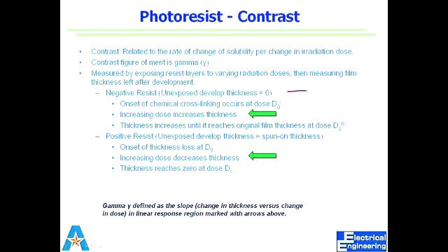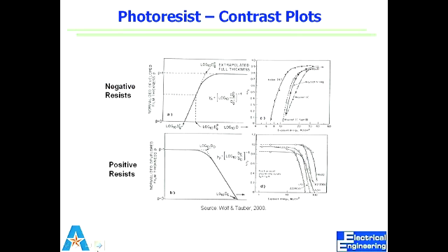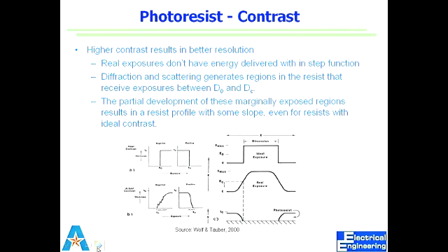That you start with unexposed thickness, which is 0. In this case, you start with the unexposed thickness, which is the actual thickness of the resist. So in both cases, our frames of reference are different. The boundary conditions are different, yes, because the reaction is different. In one case, it's making it soluble. In another case, it's cross-linking it. So which side it starts from is different. Just hang on, you'll see much more explanation on this.